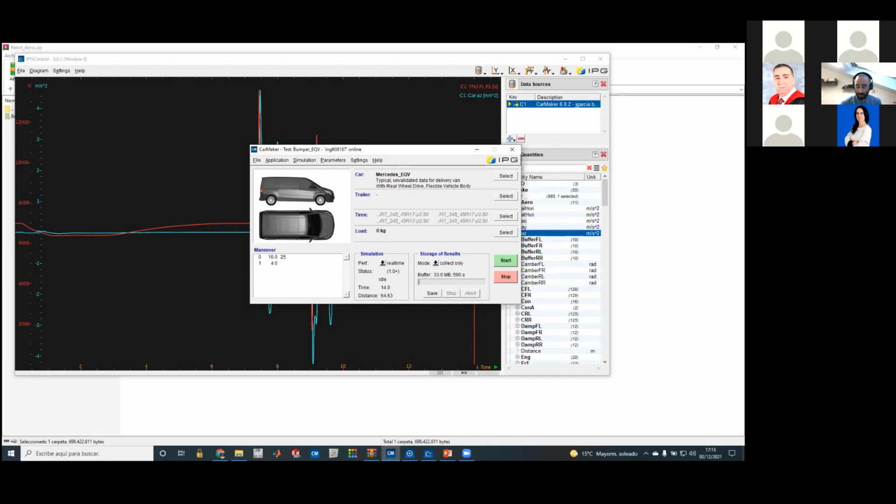For example, if I want to consider the impact of the transmission of the vehicle on the comfort, for sure I can do it, and for sure it will be a function of the RPM of the shaft. Those RPM we will translate into Hertz, and that will be the frequency of the excitation we are going to use. The amplitude of the forces can be computed from the dynamic behavior of the eccentricity of the axis.